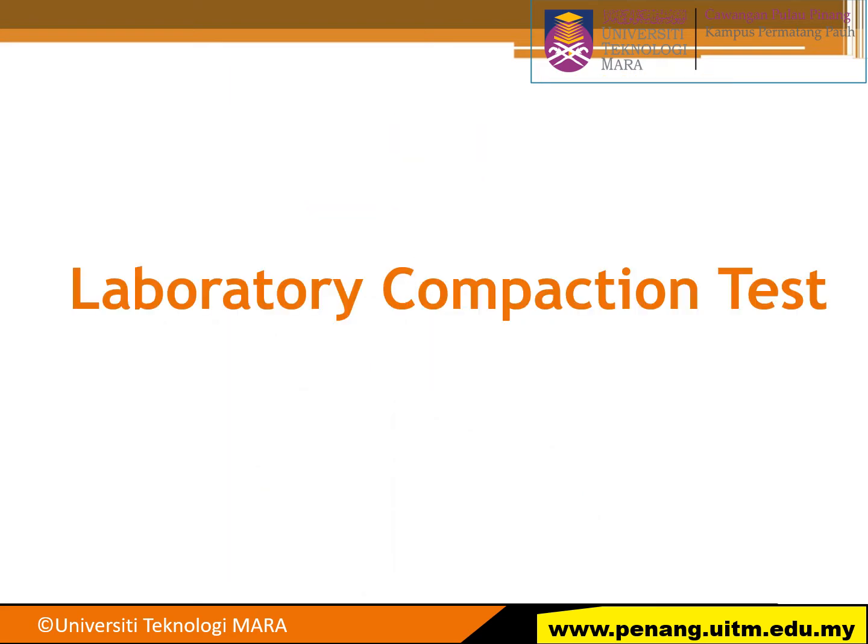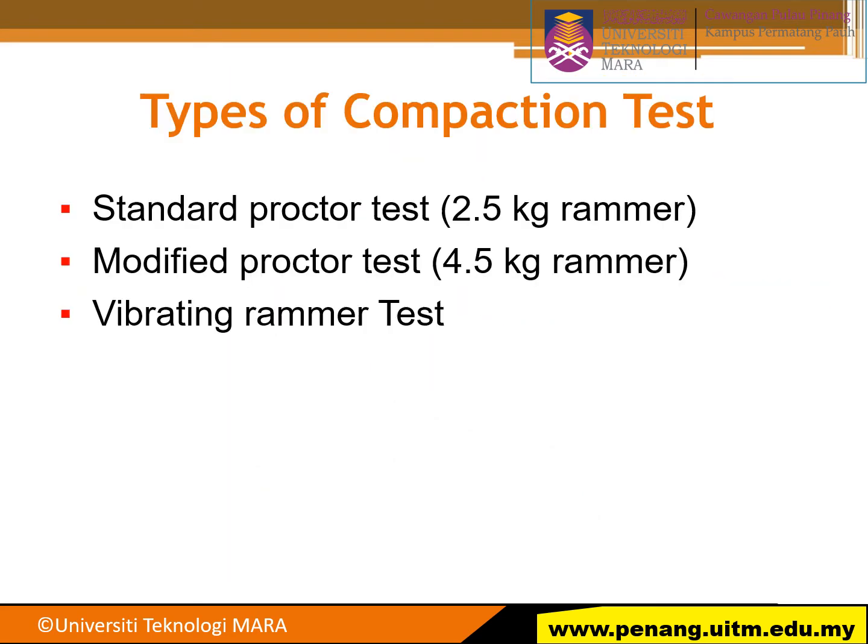Now we go for the laboratory compaction test. For the types of compaction tests, we have the standard Proctor test, using a 2.5 kg rammer, and then we have the modified Proctor test, with a 4.5 kg rammer, and the last one is the vibrating rammer test.